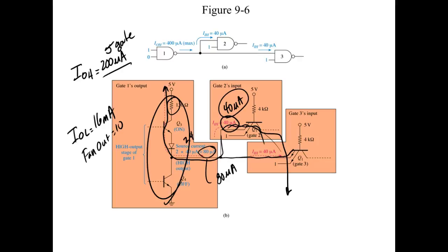So what is fan out? The fan out is the number of like gates that it can drive. So a like gate would be like a 7400 driving a 7404. It would not be a 7400 driving a 74LS04, or a 74LS04 driving a 74LS100 driving a 7404. So we're talking about like families, right? Understand, when we do the fan out, it's talking about like families.